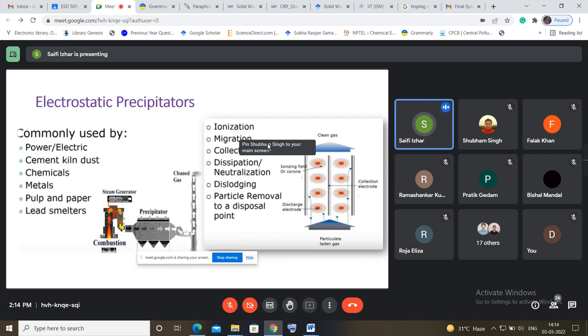So again, we are talking in the sense that a centrifugal separator has higher force compared to a gravity settler. That is why centrifugal separators are able to remove the finer particles.